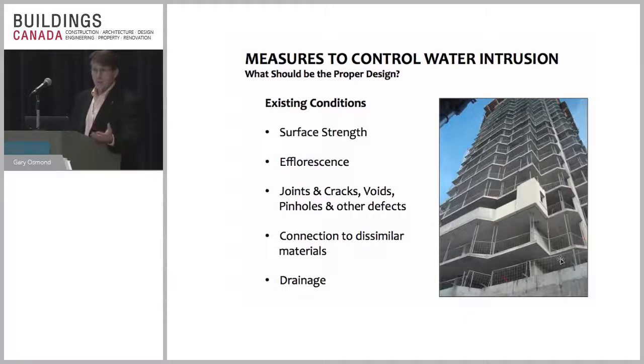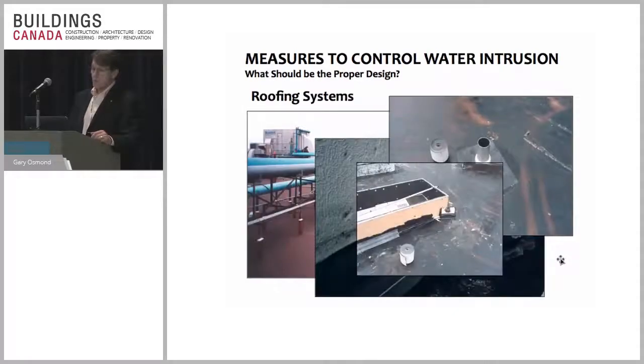Putting materials down, does it create pinholes, or do you have other problems with it? Connection to similar materials, and does it drain? Systems have to be drained. Horizontal surfaces have to be augmented or changed so that they're not going to collect water. Water's going to be able to drain away or have some sort of disposal system. Once again, the animation worked.